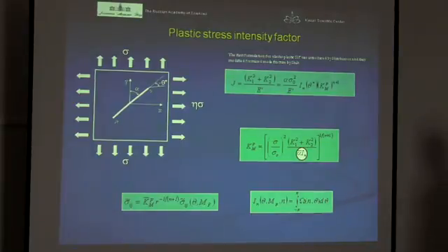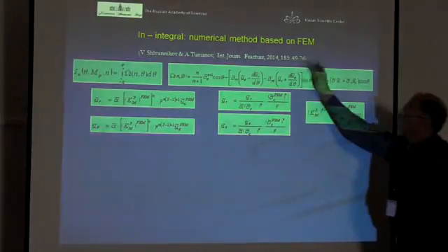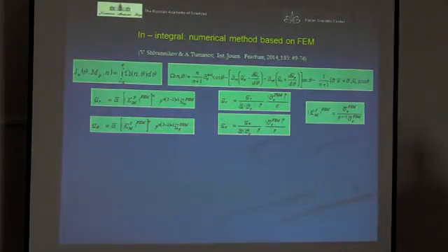The problem is how to determine governing parameters of the elastic-plastic stress field for real structures, for instance, specimens, because Hutchinson introduced and gave the values of this parameter only for an infinite-size cracked body as a function only of the strain hardening exponent. We elaborated a method for numerical calculation of these parameters on the basis of finite element results.